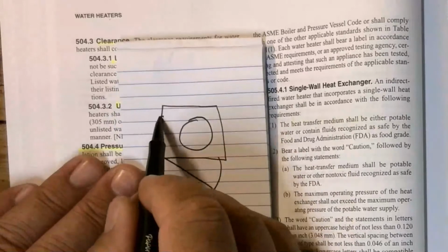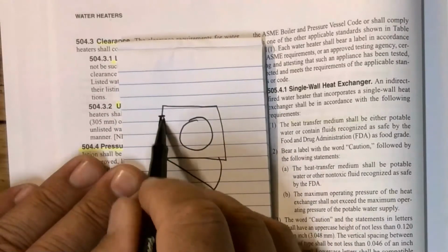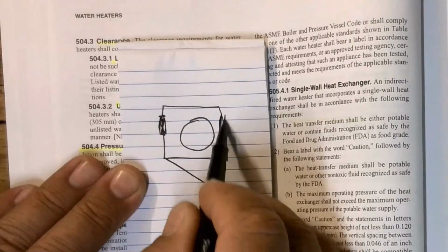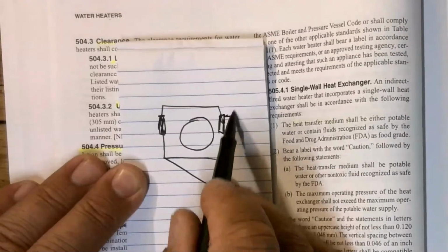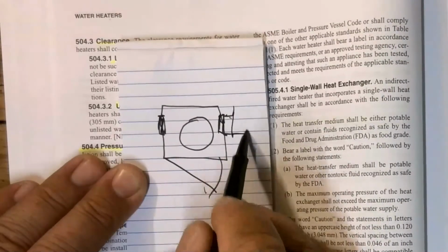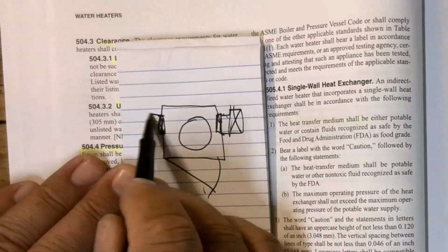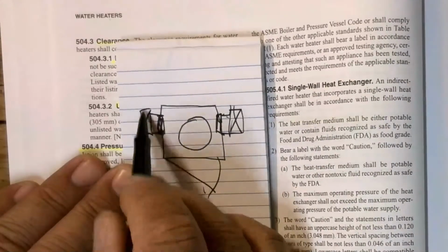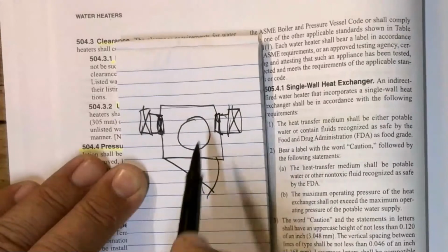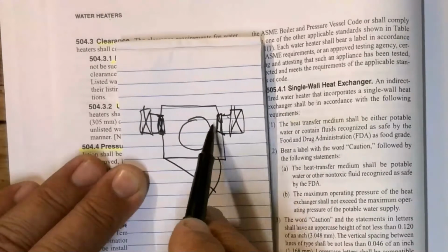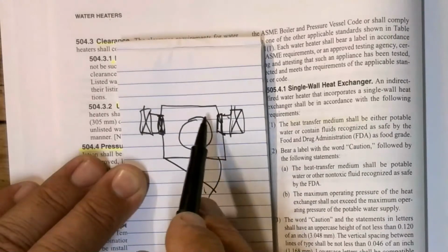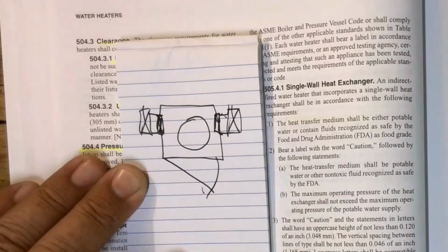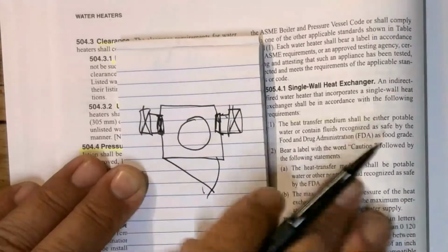Also, let's use this side over here and maybe one side over here. I've got combustion air, so in other words, I got a duct that comes in from up above, and I got another one over here that comes up from up above. The water heater can't be like butt up against here. It needs to be able to give free movement of air. Okay, that's what they mean by that.